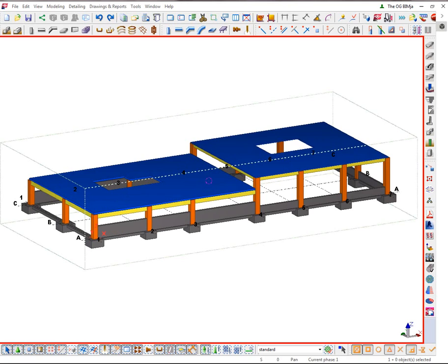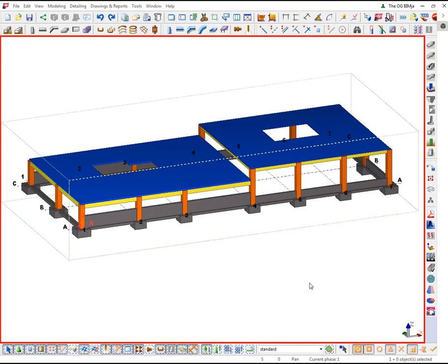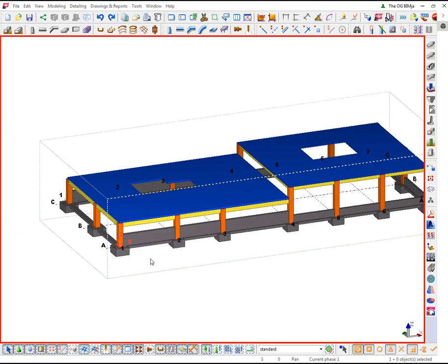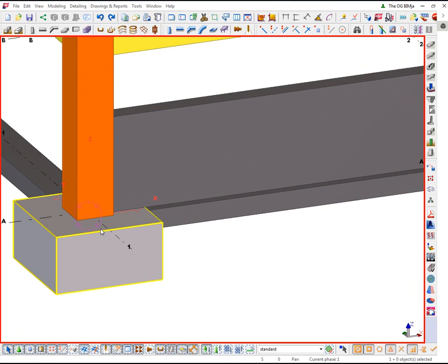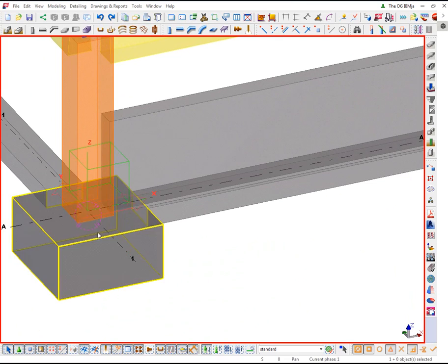This video will cover how to export your Tekla model to project coordinates for coordination. So basically what I have here is just a sample model, and I need to provide an IFC for coordination with my rebar subs or my MEP or my formwork, or if maybe I'm a concrete subcontractor sending it to the general contractor. So whenever Tekla creates an IFC, it uses by default the origin.